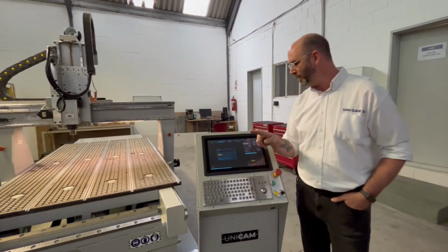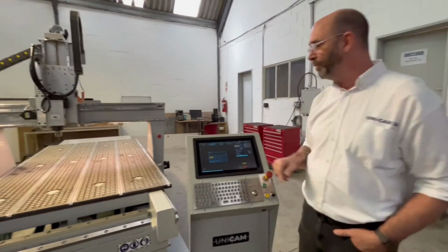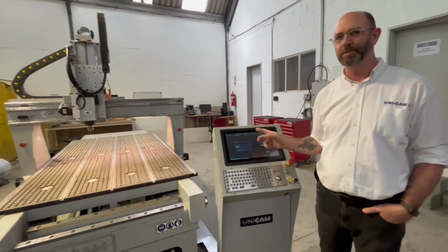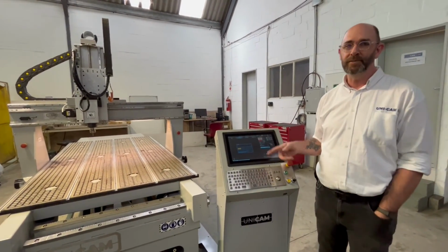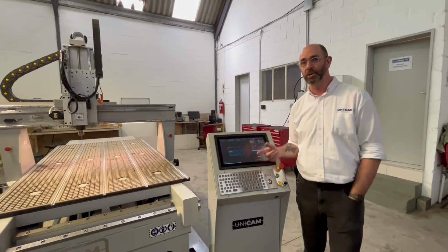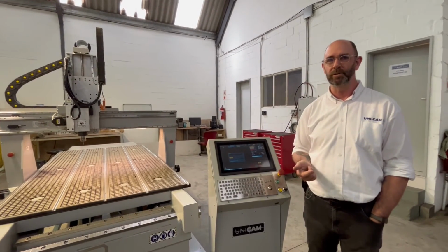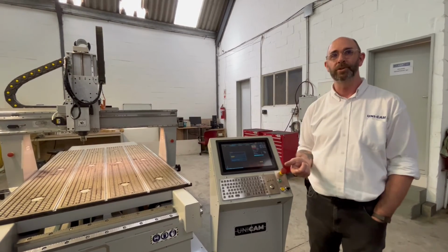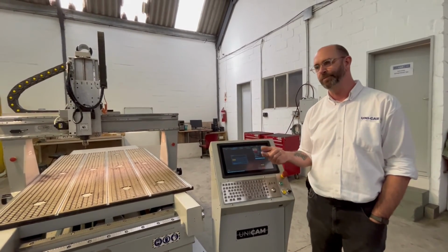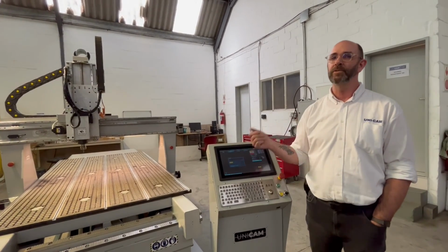But now it comes up as an error. Reason being is we actually haven't homed the machine. Now this is another safety feature that Masso includes on startup. You cannot actually run a toolpath, start up the spindle, or do anything that will cause major harm to anybody or mess your material up before you've homed the machine.